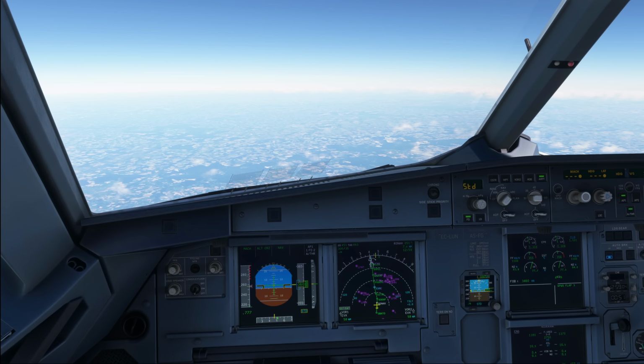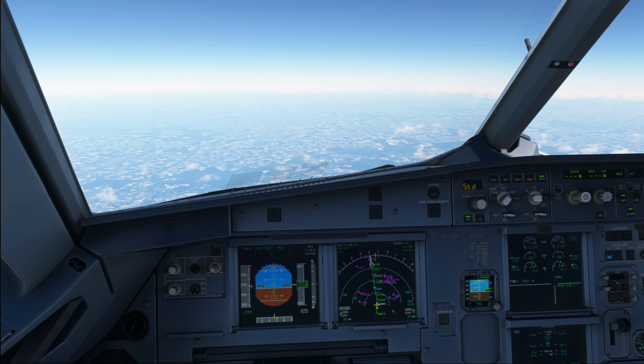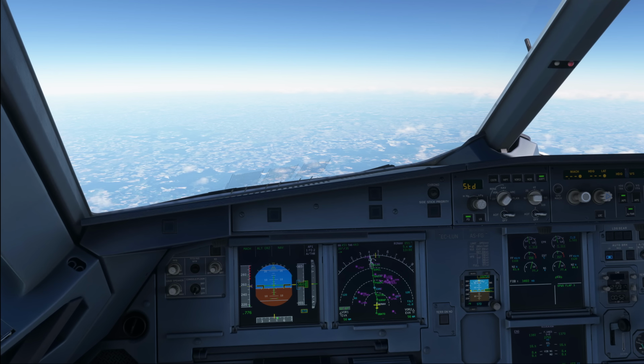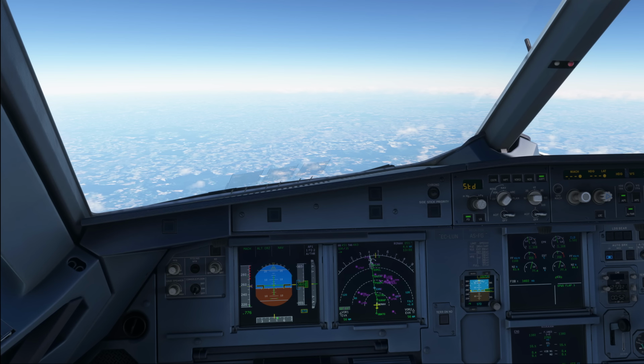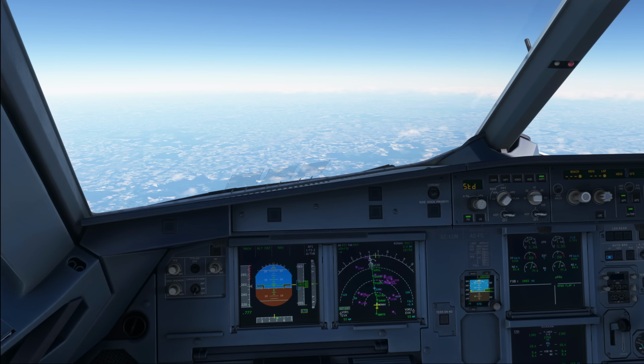So, fuel reduction is not a factor for the selection of a takeoff configuration. The takeoff performance and best takeoff configuration depend on several operational and environmental factors. The flight crew should select the takeoff configuration that optimizes takeoff performance, such as the takeoff weight, if possible increases flex temperature, and reduces the takeoff speeds, so for example a higher configuration for a dedicated flexible temperature.